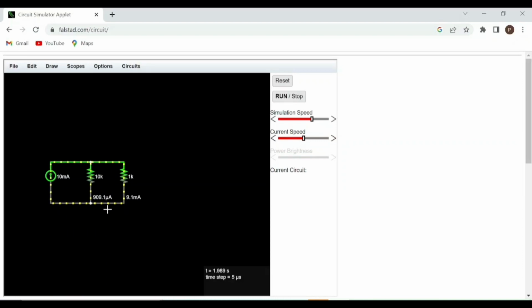This principle is used in many different circuits. In the parallel RLC circuit, you use it to find the current across any component. It is also used in the DC biasing, DC analysis and AC analysis of a transistor, that is, when we are transforming the transistor into its equivalent model, having a voltage source and a current-dependent source. Then it is very important. Also, current division is important when you are doing DC analysis and one part of the circuit has a current that depends on some other current. Then also, it is very useful for finding the current between parallel elements.